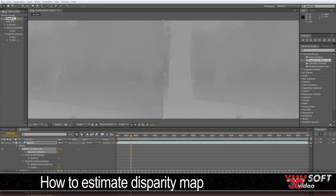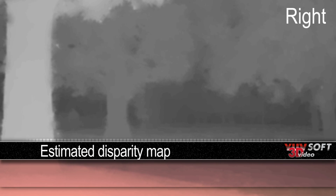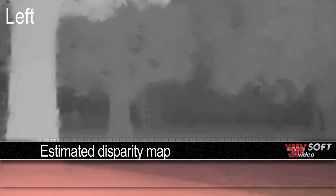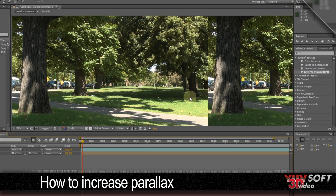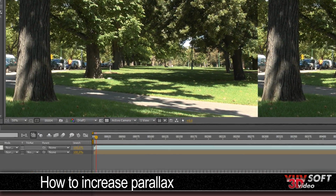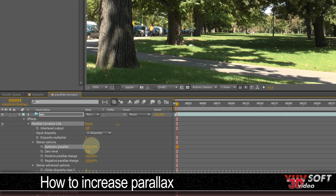So now that we see them side by side, you can see how the closer objects have lighter values and the further objects have darker values, similar to a depth pass. Now, to increase the 3D effect or parallax in the scene, we apply the Parallax Corrector plugin, and then we assign the disparity map we just created with the Depth from Stereo plugin and assign the same disparity multiplier to match. And then to increase parallax, we simply increase this summary parallax setting.